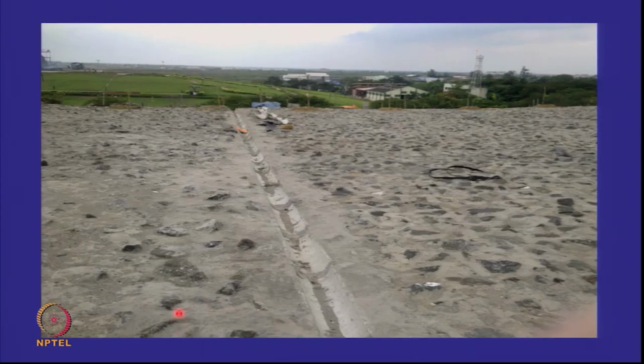And two issues here. If this settles with time, there are going to be a large number of cracks. You can repair it, no doubt about it. But this is a hazardous waste landfill. It's not settling that much. You can't use this on a municipal solid waste. There are huge depressions on municipal solid waste landfills with time.